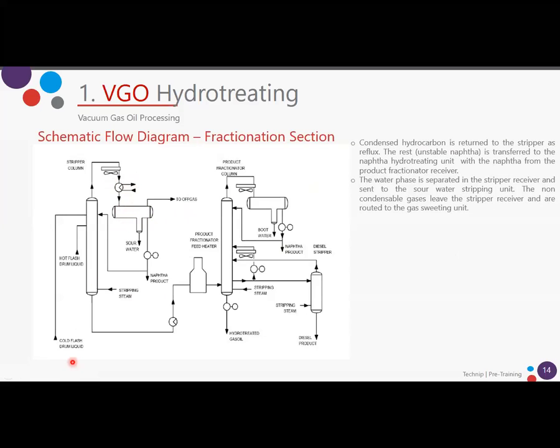The condensed hydrocarbon here is returned to the stripper as reflux, and part is sent to the naphtha hydrotreating unit.